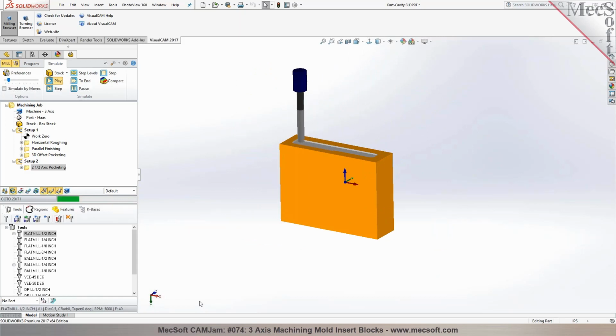Would you have any parts that require machining from more than one side? Yes. Okay. So this is one of the benefits of being able to do it in the Pro, so you can program from multiple different orientations within the same part without having to create multiple copies of the part to program from each orientation.